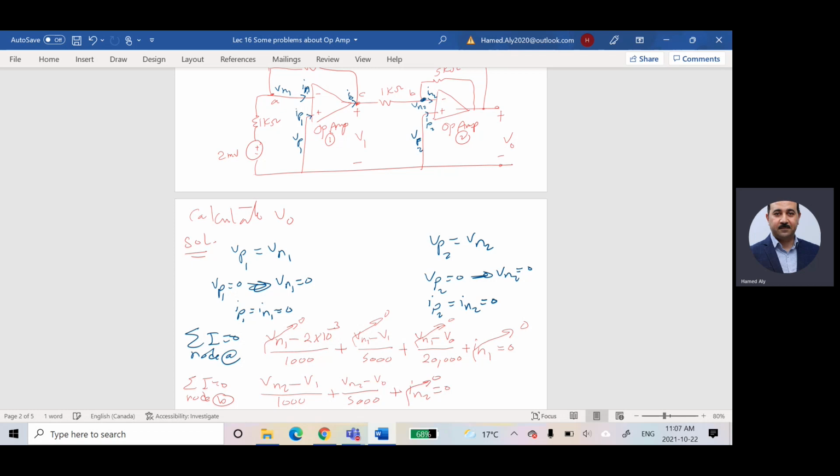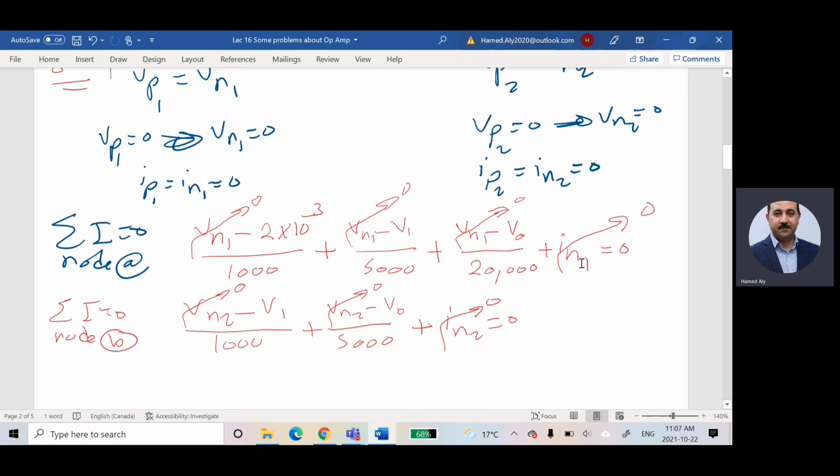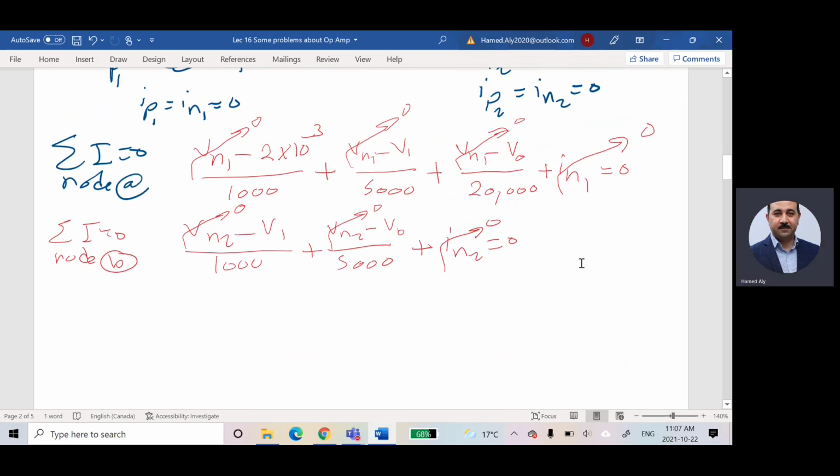You told me that this guy is 0. You told me that this guy is 0. You told me that this guy is 0. Then I have two equations in two unknowns, which are VO and V1. I can solve these two equations for finding the value of V1 and VO. If you try it, you will find that V1 is equal to 40 millivolt, and you will find that VO is equal to negative 0.2 volt.